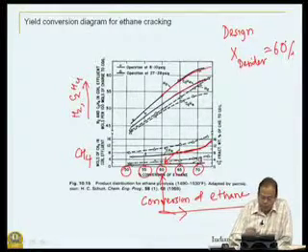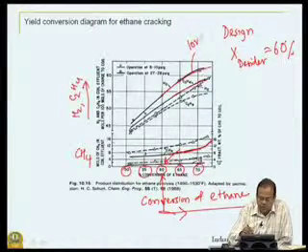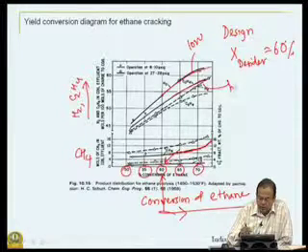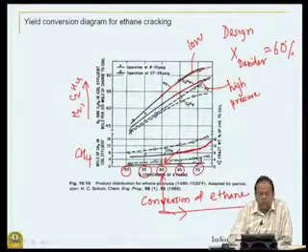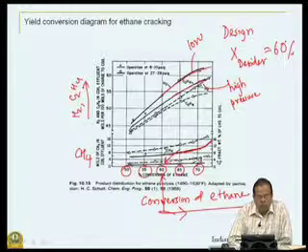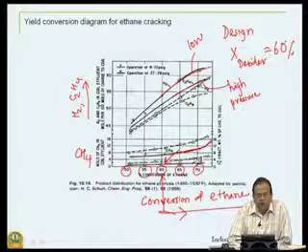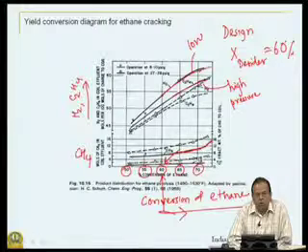The second aspect that is also apparent is that here we see the results at two different pressures. This is low pressure and this is high pressure. Now, why is this happening? Because there is an increase in the number of moles, lower pressure will favor higher equilibrium conversions. So, typically the operating pressures are on the lower side, but then there is also another limit.